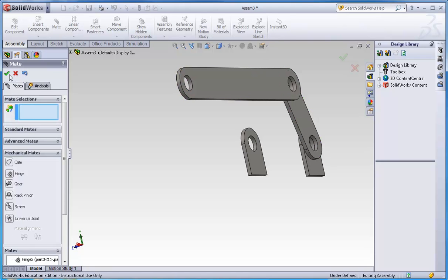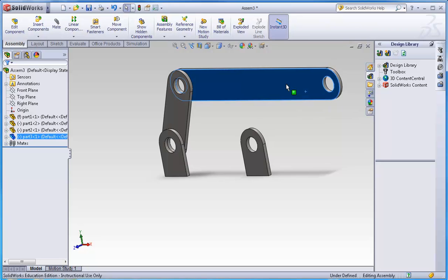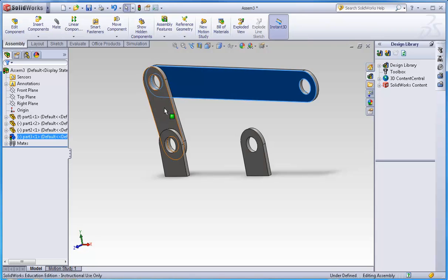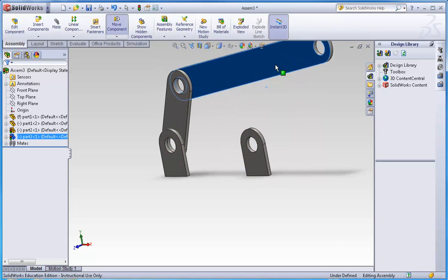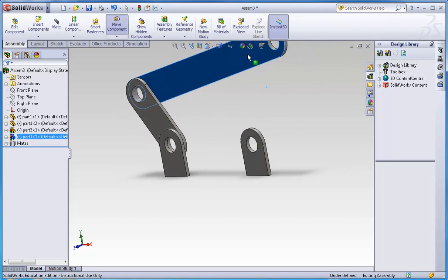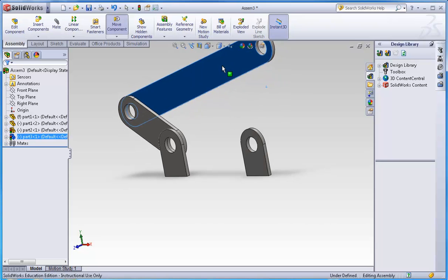I'll accept that joint completely, rotate around a little bit, and I can grab this part, and I've got a connection that moves both. Or I can just grab this part, and this one just stays without changing angle. Alright, I've almost got a closed loop mechanism. These two cannot move. Right now what I've got is a little 2 degree of freedom robot. It can move, if I put motors and control this thing, it can move in planar space to just about anywhere that's within its reach.